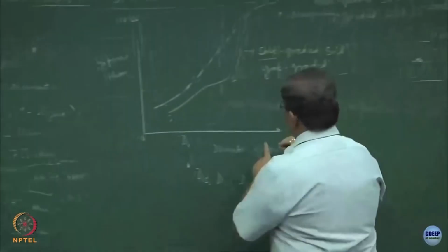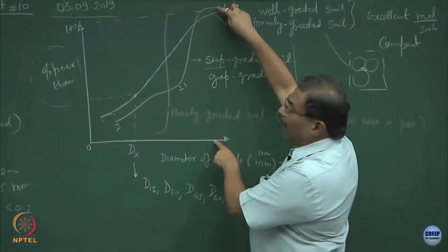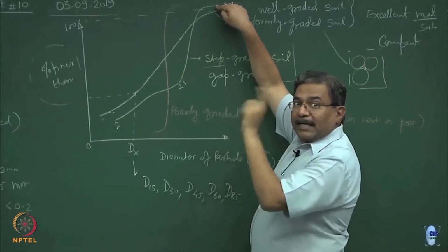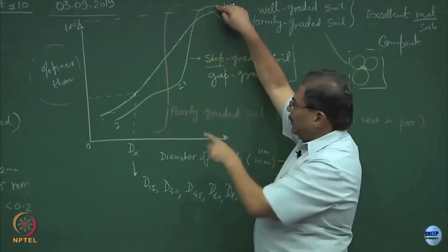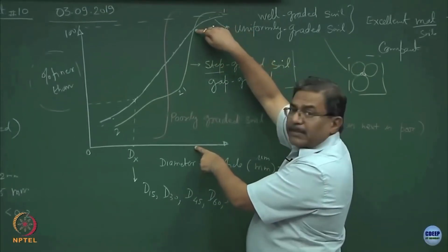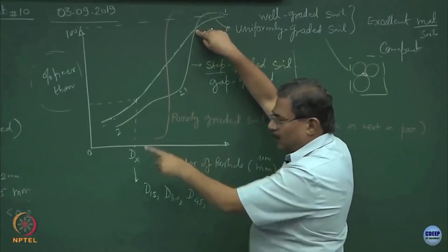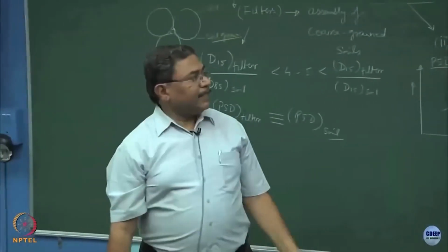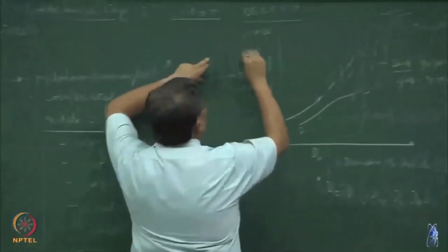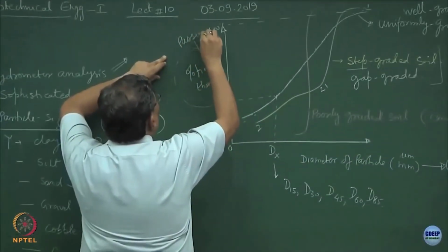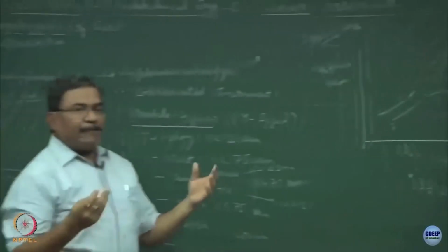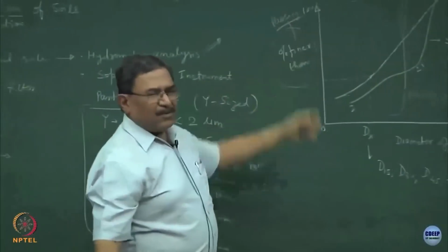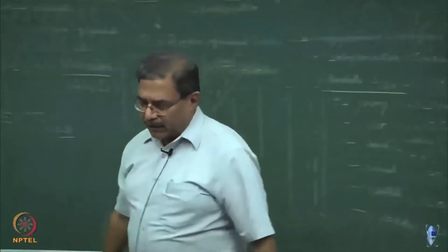It is good that you have asked this question. So, for the biggest particle, everything is far finer than this, everything passes through this, agreed. The second sieve size is lesser than the first one, less particle size, 80% finer than this, agreed, and so on. So, it is good that you have asked this question for the sake of everybody. Percentage finer is also the same as the percentage passing. Anything which is finer than that particular aperture is going to pass through that sieve, and hence it is finer, but it is passing also. It depends upon what you are using.